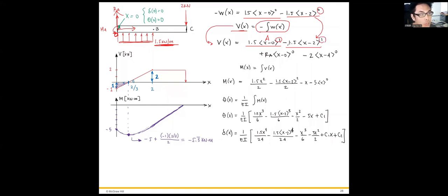And also there's shear force from the reaction or the point load. RA is the reaction at this point A, which here is minus 1. Also it's to the power of 0, since at point A we define it as the origin. And also there's the point load applied at point C, 2 times x minus 4.